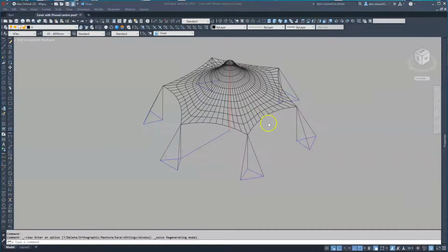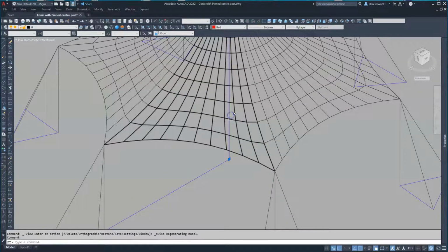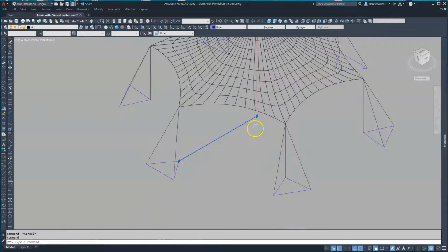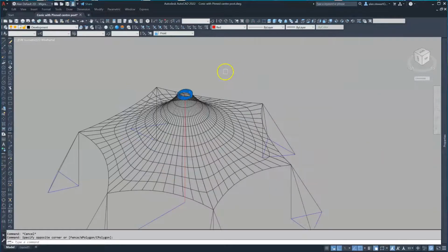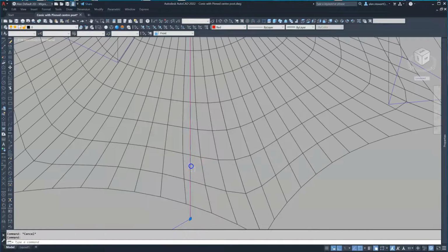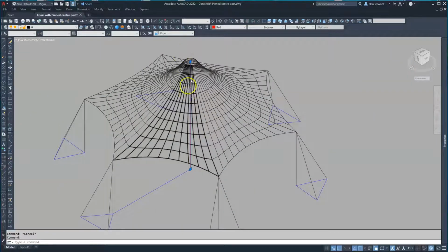down to the ground. So in the first example, we've got a 3D polyline that is the center post. The base of the center post is fixed with another 3D polyline, and each of the perimeter posts has two backstay cables and a 3D polyline anchoring each corner. The bail ring itself has been colored red. This can be any color, but I've selected red, which is color number 1 in the AutoCAD colors, as has the 3D polyline. So the two of them are both colored red.